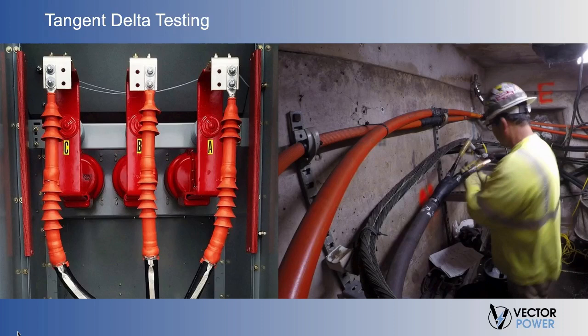In a cabling system, the terminations and splices are part of that system. If the insulation of the system and all accessories are free from defects like water trees, electrical trees, moisture and air pockets, etc., the cabling system approaches the properties of a perfect capacitor, as we stated earlier.